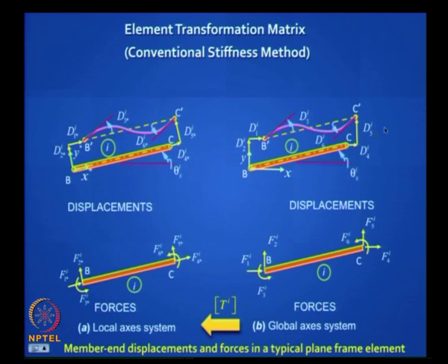The boss here is the central government, that means the global axis is your foundation and from that you switch to the local axis, and you do it through a linear transformation using a standard matrix called the Ti matrix. It is a transformation matrix. Can you work out a relationship of this matrix? What is the size of this matrix?